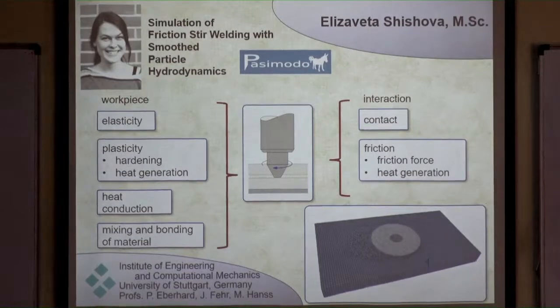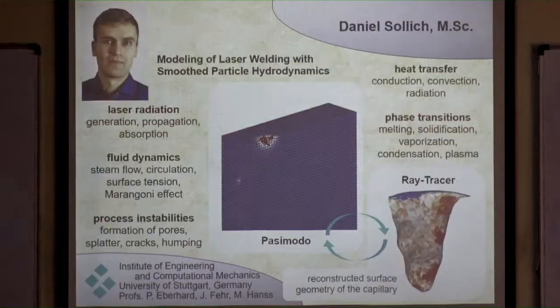It's not melting. If it's melting, then it's welding. This is another thing, I will come to this. No, it's softening this material, and then you smear the material into each other. The nice advantage is that the seam weld is of extremely high quality. It's very, very stable. You use something like this very often, for example, for planes, for aeronautical industries.